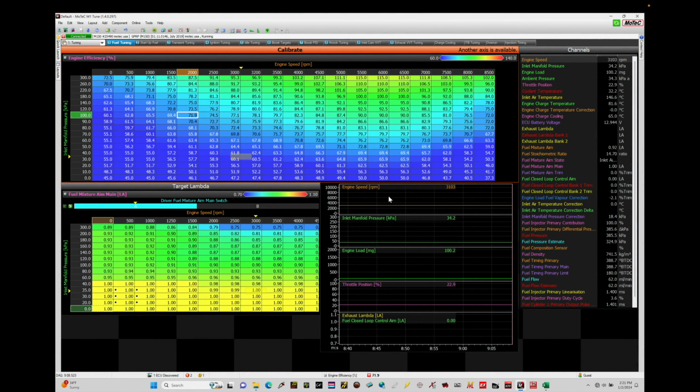Okay, so let's get started. We're going to be taking a look at working with our fuel injection timing programming found in our Motec M1 system. Now, the focus of the tutorial is going to be on port injection engines, but we will be touching on the fuel injection timing within a direct injection engine because it's handled differently in terms of what we program and what the values actually represent.